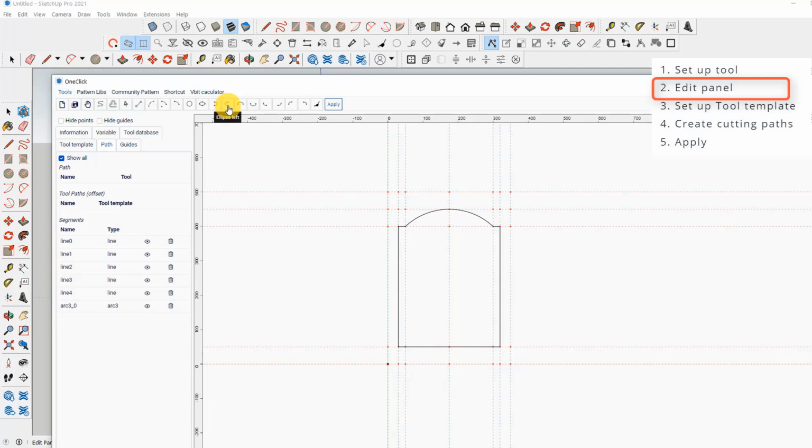For ellipse right, left, top or bottom, select the tool and select the 2 points on the x-axis. Type in the value 50 for example. And for ellipse top, 2 points on the y-axis. Then type in the value. And do similarly for other ellipse parts.